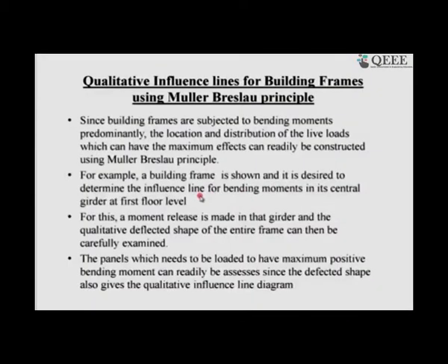In your slide, we will demonstrate how useful the Muller-Breslau principle is to draw the qualitative influence line for building frames. Since building frames are subjected predominantly to bending moments, the location and distribution of the live loads which can have the maximum effects can readily be constructed using the Muller-Breslau principle.